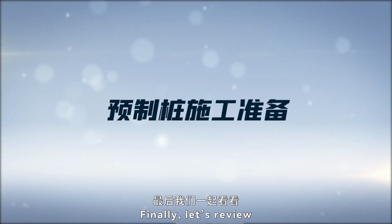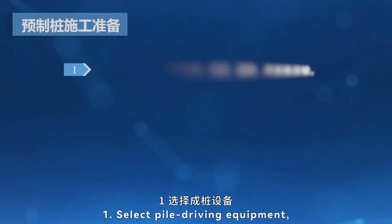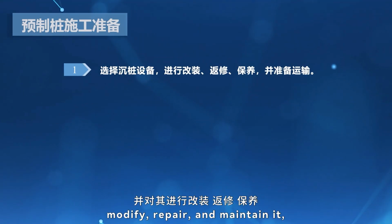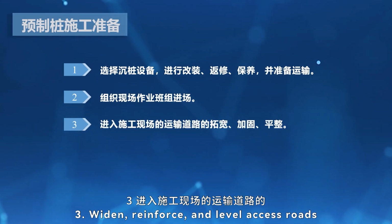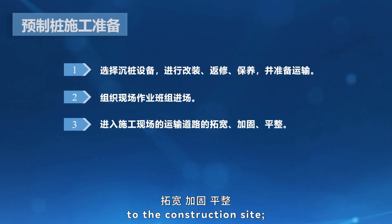Finally, let's review the construction preparation for prefabricated piles. 1. Select pile driving equipment, modify, repair, and maintain it, and prepare for transportation. 2. Organize on-site construction teams. 3. Widen, reinforce, and level access roads to the construction site.